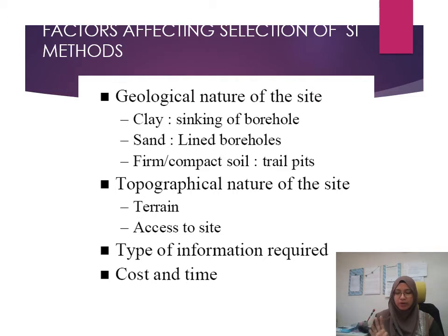So there are 4 sets of factors that you have to take into consideration in selecting the method. Right, so number 1 is geological nature of the site. Number 2 is topographical nature of the site. Number 3 is the type of information required. And then lastly is cost and time.